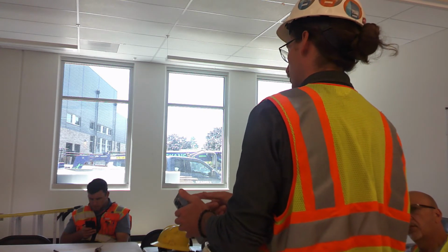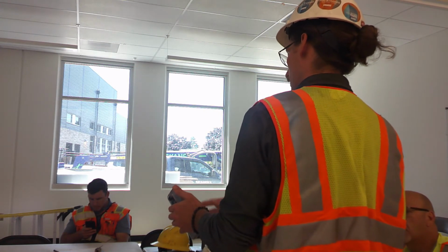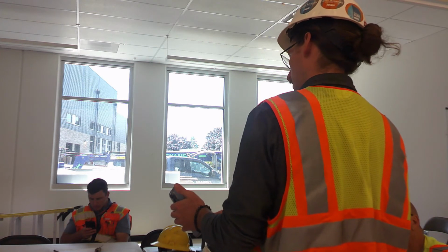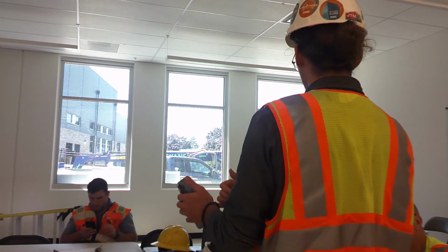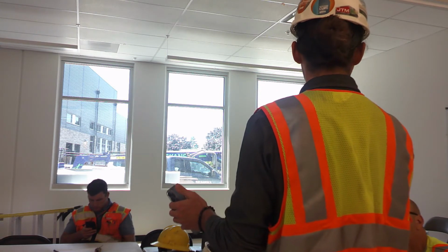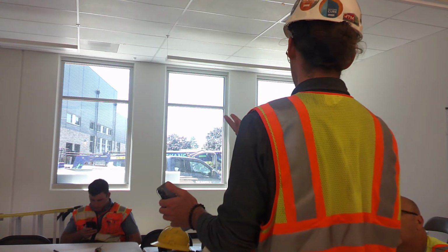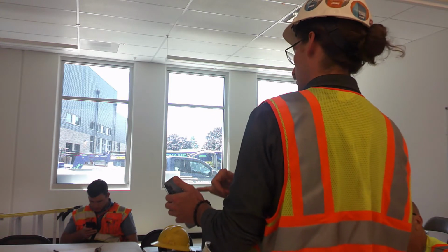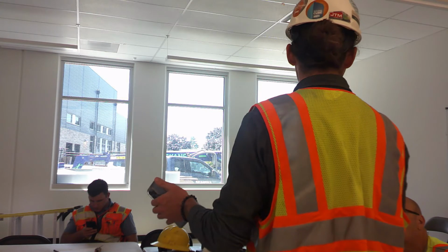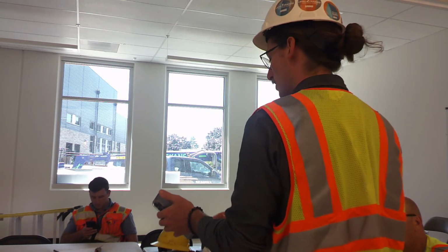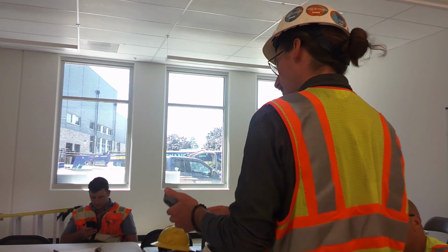So this is where I'd actually be able to go and change how the relays and dimmers work. Some of the typical things you might be concerned with are the occupancy mode. That determines if it turns on automatically with the sensor or if you have to use the switch. So all your classrooms are on vacancy per Washington Energy Code. So you got to use the switch to turn them on.